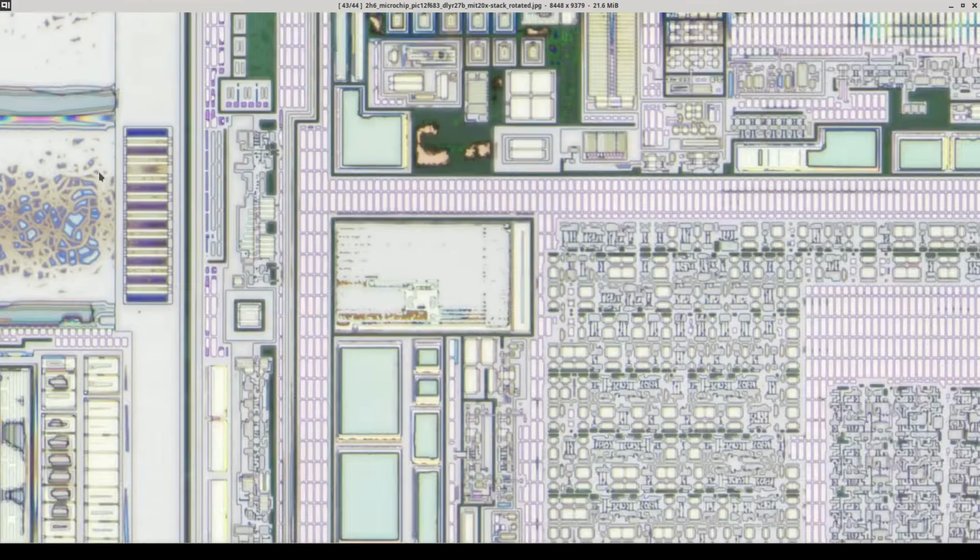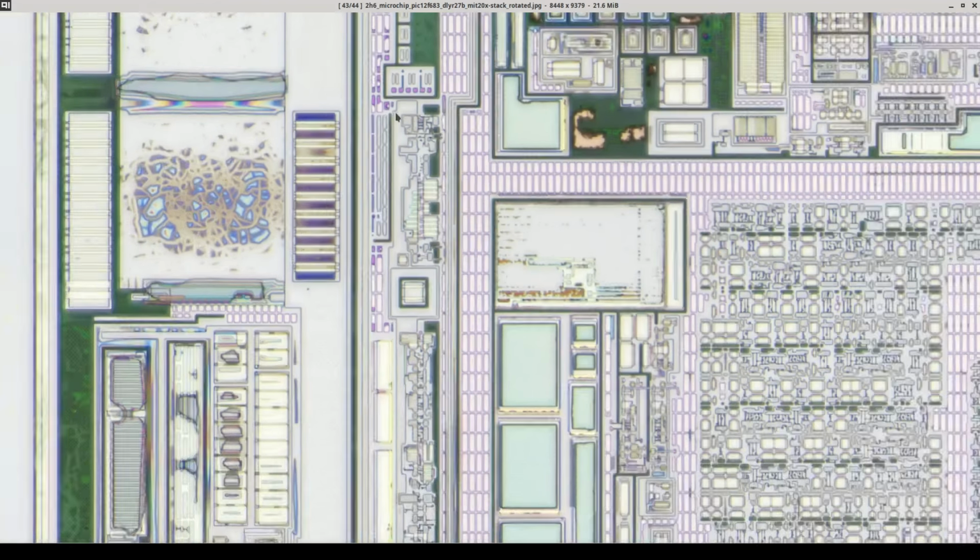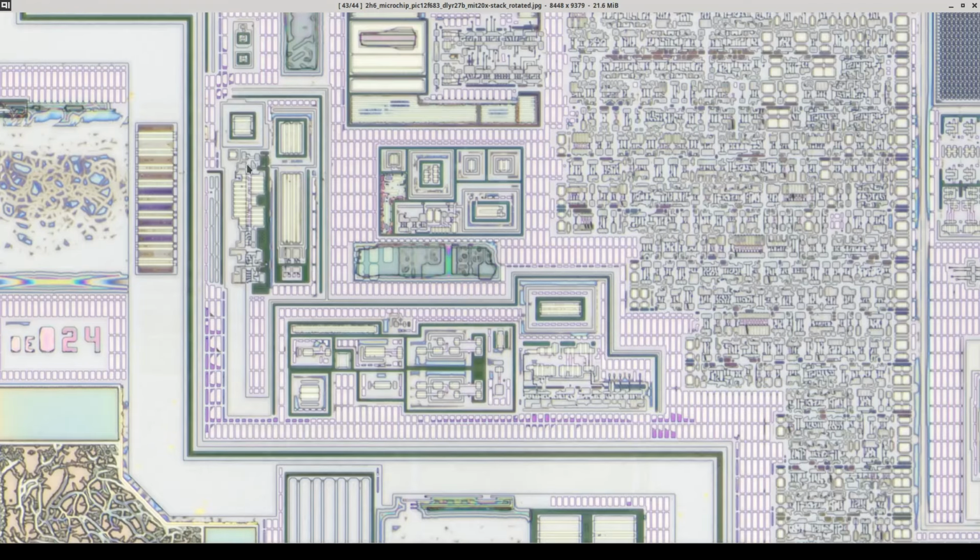And looking at some of the other I/O pins, we can see very similar. It looks like some bigger, wider transistors. These might be for higher voltage tolerance, 5-volt inputs, and so on. And then some smaller, internally driven circuits. Then going down to the bottom left corner, we see again a fairly similar I/O buffer circuit here.